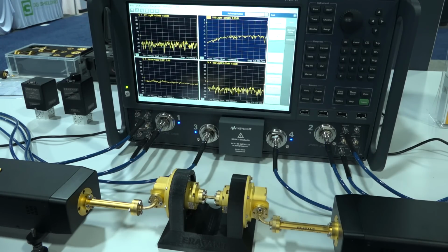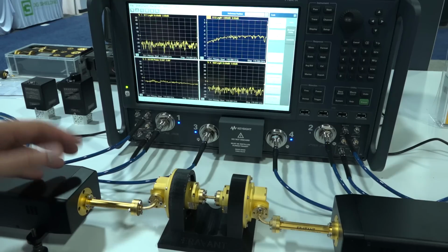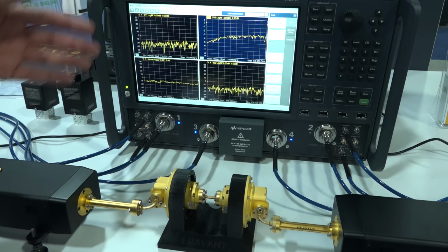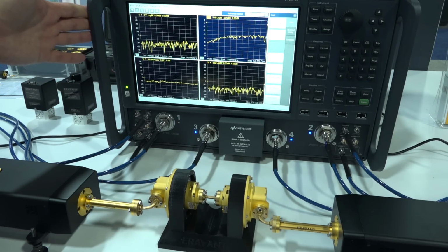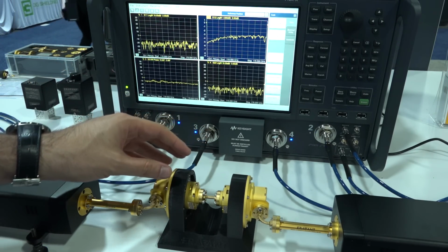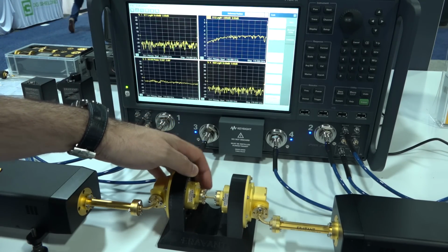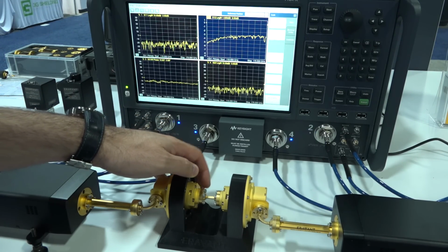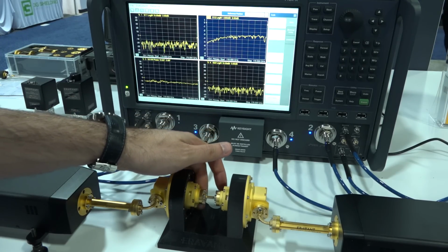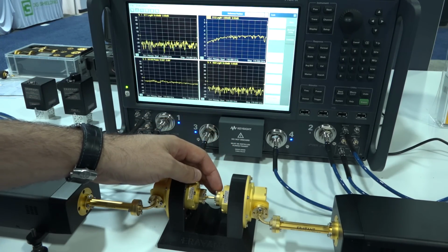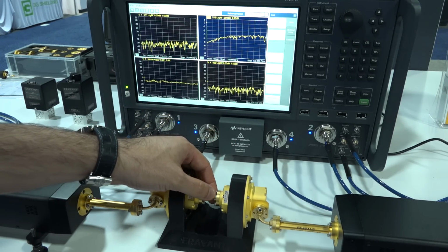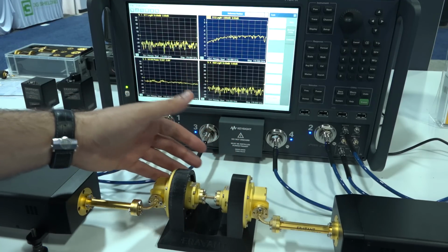And here at Eravant, the number of components they have continues to grow. So this is their D-band setup. I think we saw this last year, D-band network analyzer in conjunction with the PNA-X from Keysight. But now they have this rotary joint, high-power rotary joint. Look at this. This is a D-band interface. And look how stable the S parameter is as I rotate this. So you can imagine this is super helpful in situations where you have, for example, some measurement you're trying to do and you're trying to move things around, but there's a lot of cables in the way.